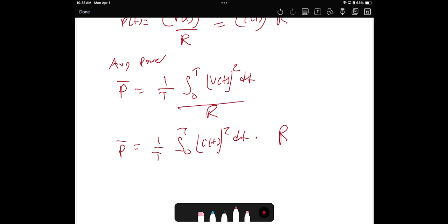We can find the Fourier series and analyze it, or we can do the integration, whatever you want. How about if it's triangular or sawtooth? You can find a Fourier series for it, and find the power in an easier way. So again, when we are dealing with non-sinusoidal signals, they are more complicated. Therefore, to find the average power, this is the overall formula.